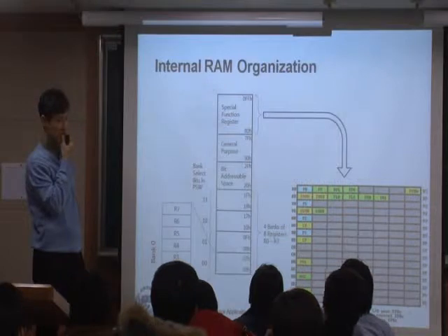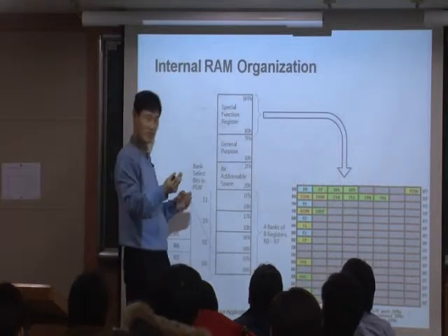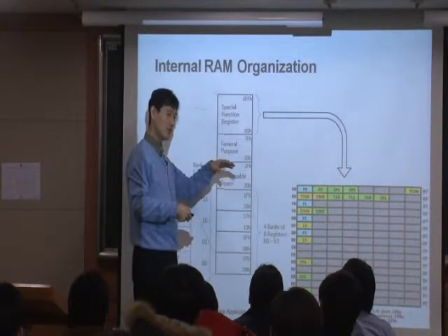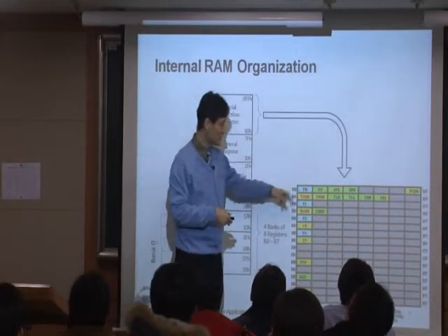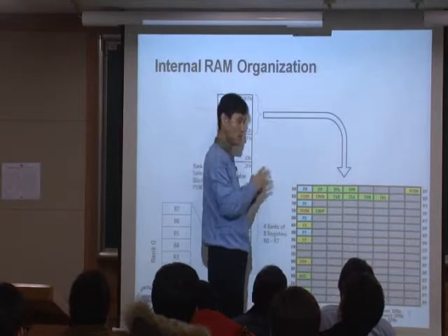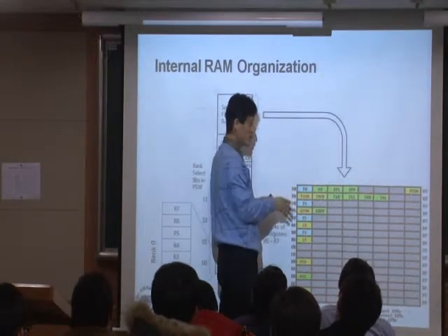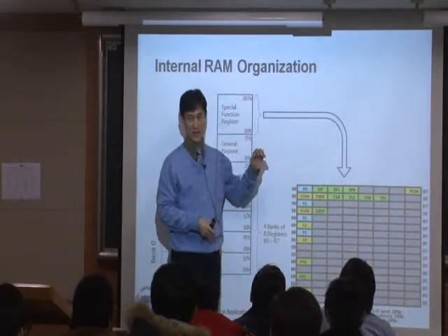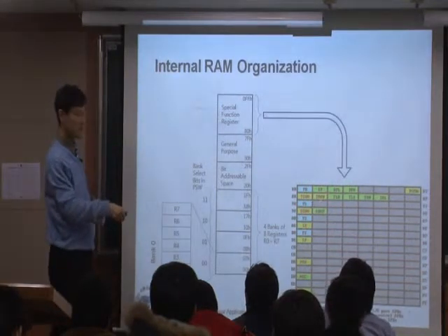Controlling what? Such as what? Yeah, exactly. That's what I said, right? I just said that you can use port 0 as an input or output. But you have to say here, okay, I'm going to use port 0 as an input. In that case, maybe you write all 0. If I want to use port 0 as an output, then maybe you write all 1. I'm just giving you an example, okay? So that's the purpose of these port registers.